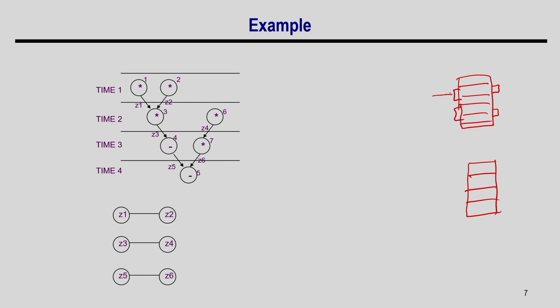If I put an address here, give data here, and give a write enable here, then the data D will be stored in the corresponding register, say register I. Similarly, if the write enable signal is 0, that means I am going to read, so the data input does not matter. I access this register and the output will come here. So, this is the port, and similarly this is port combination 2.